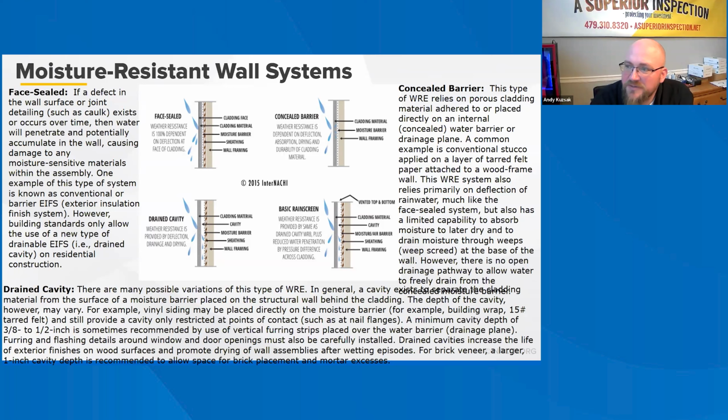At a minimum, this approach involves the use of an air barrier behind the cladding to resist wind pressures. Thus, wind pressure across the siding, which is vented and not airtight, is reduced and is less likely to result in water being driven through the siding due to pressure differentials across the siding.